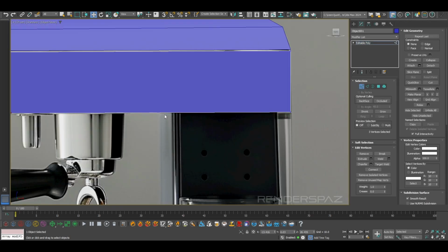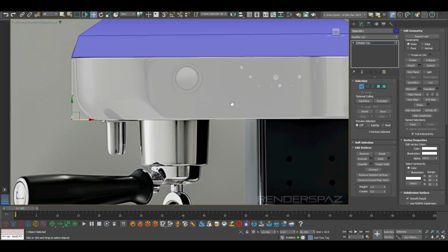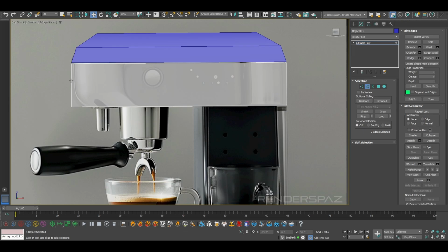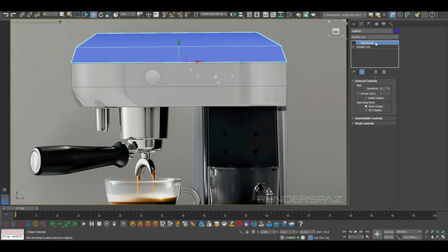We're going to do the same thing here at the bottom, bring this up or drag it in the X. Or actually, maybe I'll just select all these. Hold on a minute here. Let's go to ring and connect. And now if we drag this bottom guy over, there we go. We're going to start to get that nice little bevel there, a rounded edge, a rounded front piece. All right, just drag those lines down.